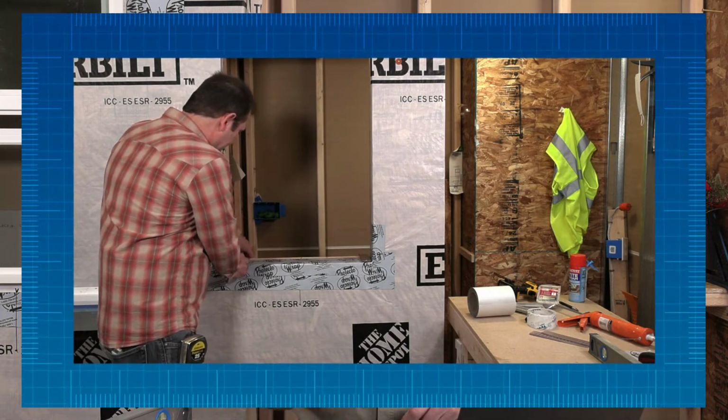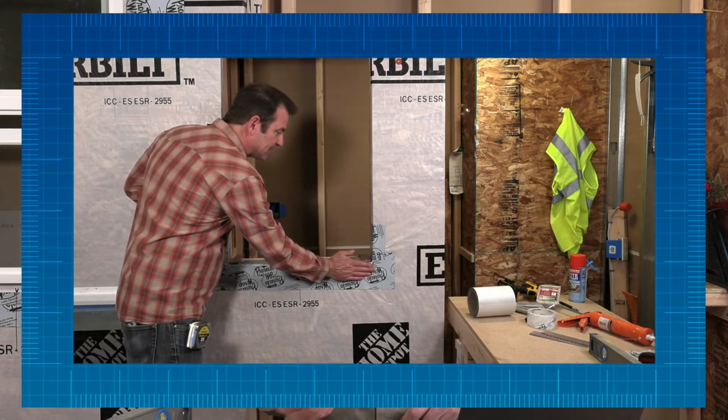The next benefit of shims is structural support. A lot of installation instructions point out or spec out shims in specific places on the window, especially if you're using vinyl windows. Vinyl tends to flex a lot, and without the shims, the frame of that window cannot stay straight or square.